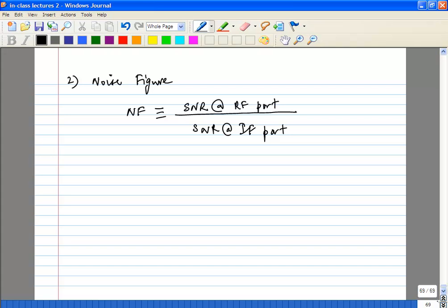That is very easy. You can just do it the normal way, the way you would calculate your noise figure. But just keep in mind there are a couple of things you need to know, which are special to the case of mixers, which you wouldn't have encountered in LNAs. There is one case for noise figure and there is one case for IIP3.